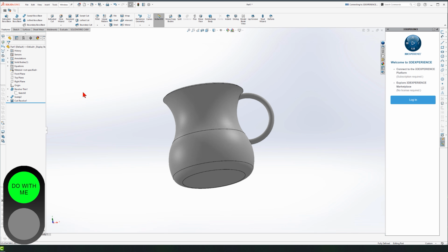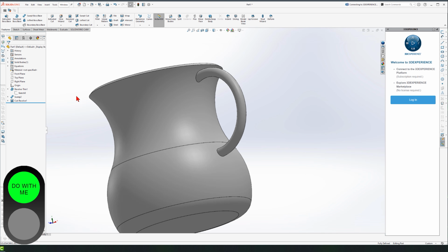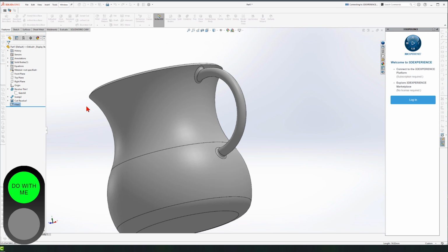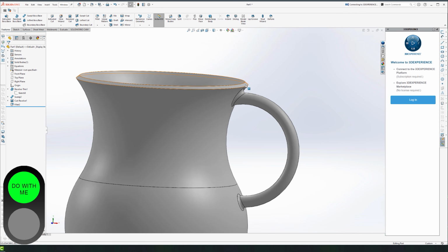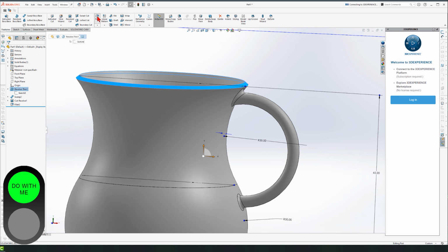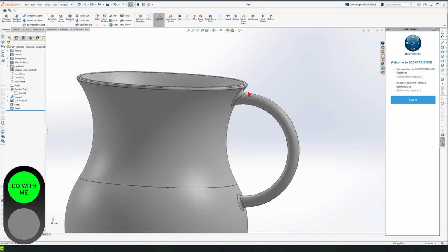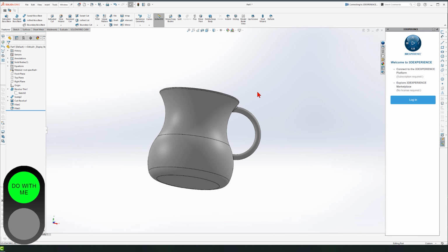Now we have our can, we have the handle, and if you want to make it look even better, why not pick fillet and select their contact point like this, even with a bigger value, maybe 2 or 1. Now we have this. And if you have sharp edges, select the surface, go to fillet, smaller value, 0.5 millimeter, and no sharp edges anymore. Boom. All right?